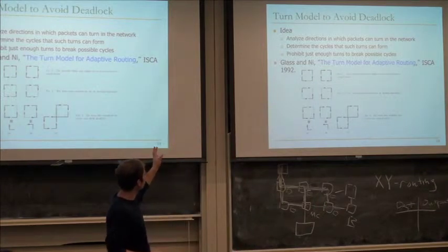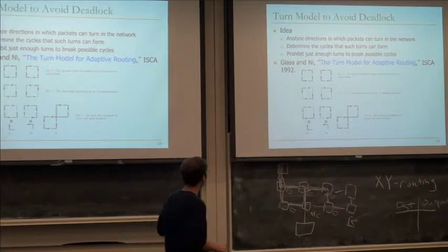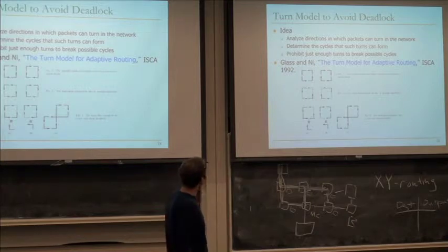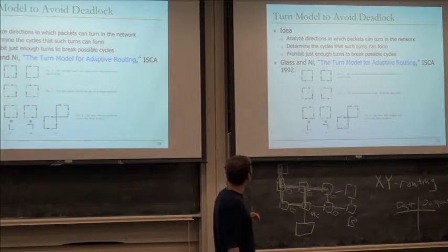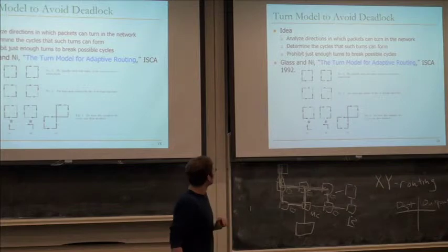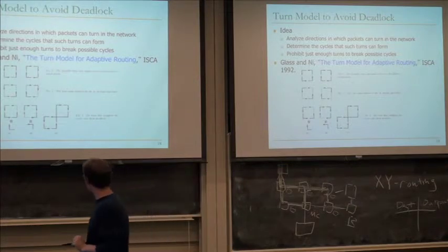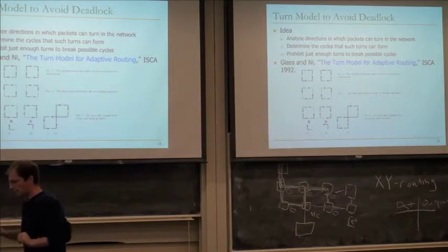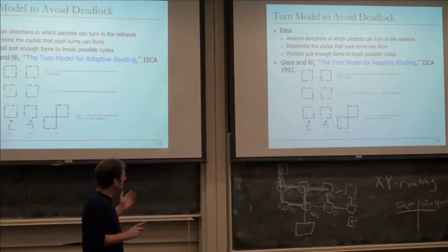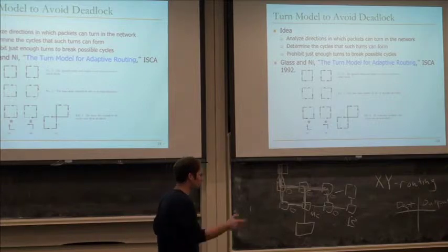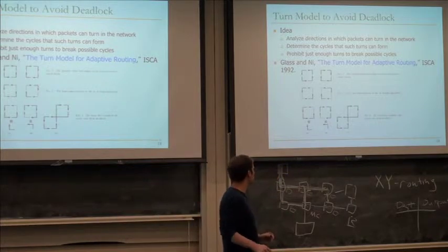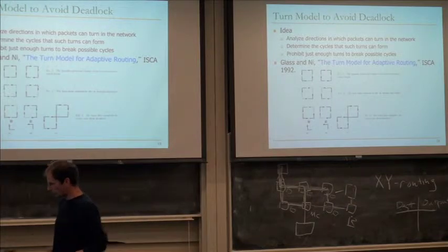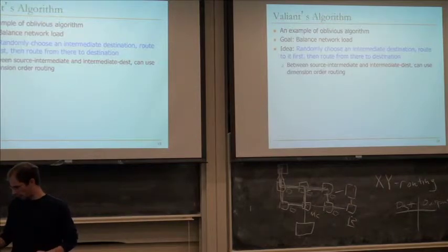And so the idea here is just to remove turns that you can make. So a turn connects one buffer to another, right, input buffers. Remove turns such that you don't have deadlock. OK. And so there are some examples here. You can sort of form these figure-8 type things where if you want to make a right turn, for example, maybe you have to go around and do a 3-stage left turn instead. But that actually removes the cycles in the network. So you can read the paper for more details there.